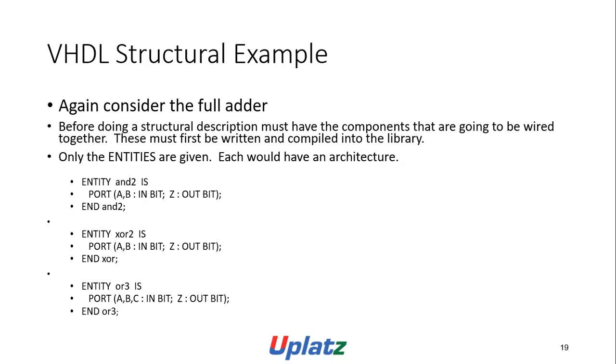Entity AND2 is port A, B in bit, Z out bit. Entity XOR2 is port A, B in bit, Z out bit. Entity OR3 is port A, B, C in bit, Z out bit.